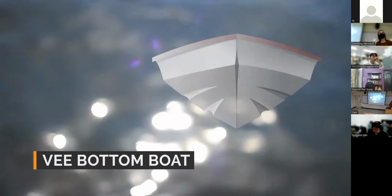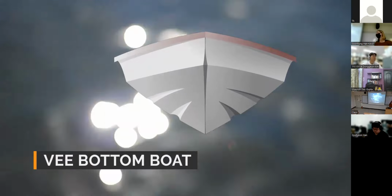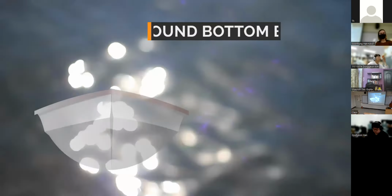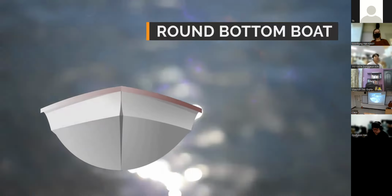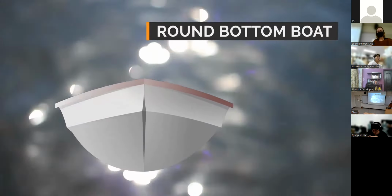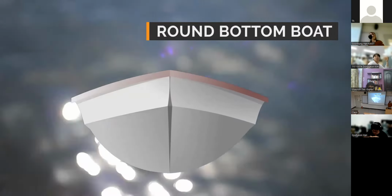V-bottom boat. The V-bottom handles rough waters, but needs more power to achieve the same speed. Many runabouts use the V-bottom design. Round bottom boat. It moves easily through the water, especially at slow speeds, but tends to roll unless fitted with a deep keel or stabilizers. Many trawlers, canoes, and sailboats have round bottoms.